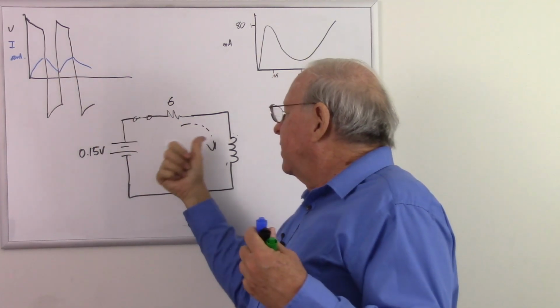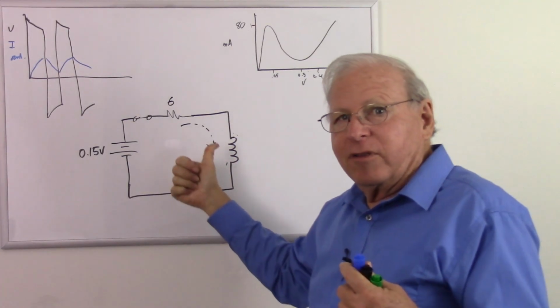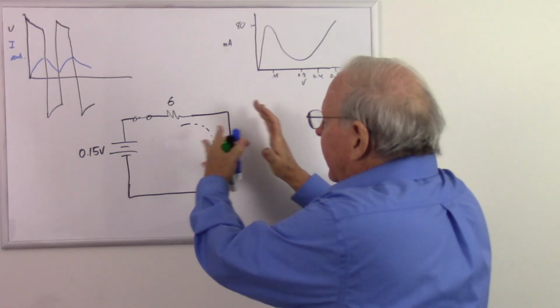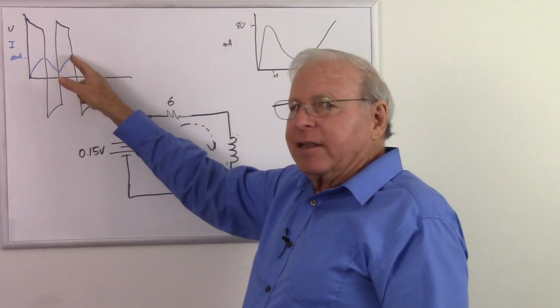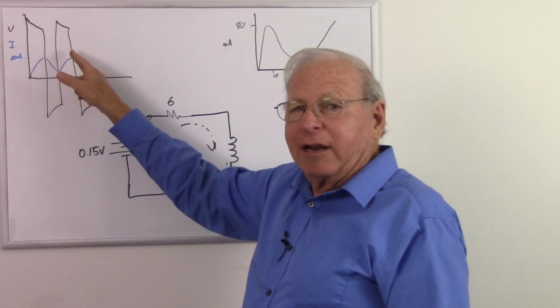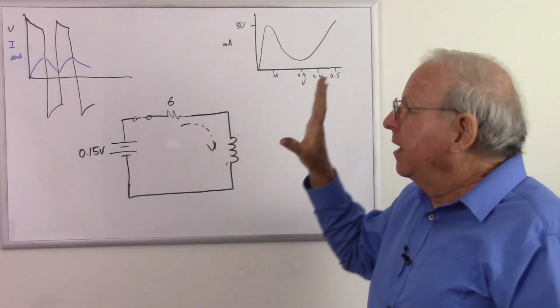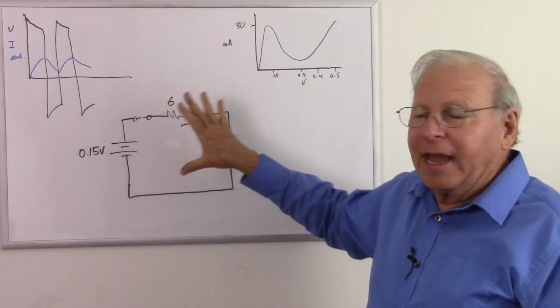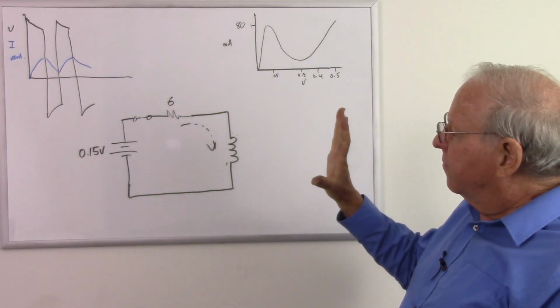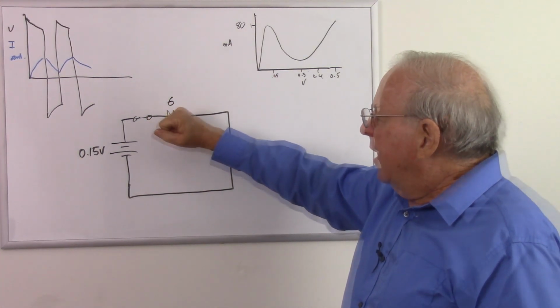And so now this starts going back through its increasing magnetic field cycle. And then when it gets to 80 milliamps, it suddenly switches back to a high impedance. And so we get that hysteresis. So in a nutshell, I've oversimplified how this works. So let's take a quick overview of that. At first,